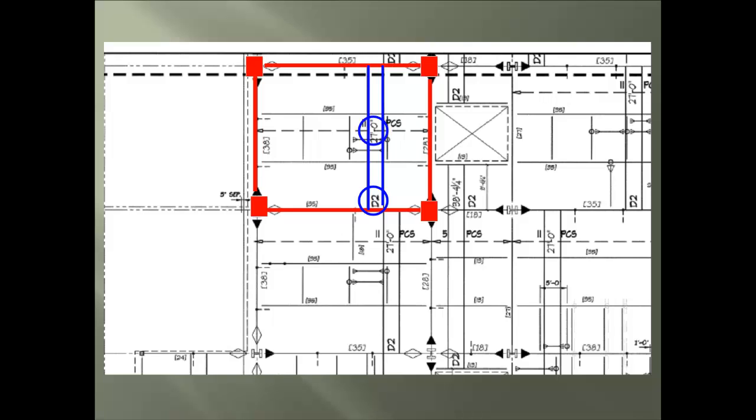And this is the length of the bundle. Now we see the call out of 11 pieces, which means within this one bundle there are 11 single sheets of metal decking that will start here and connect together by their edge connection until they reach here.